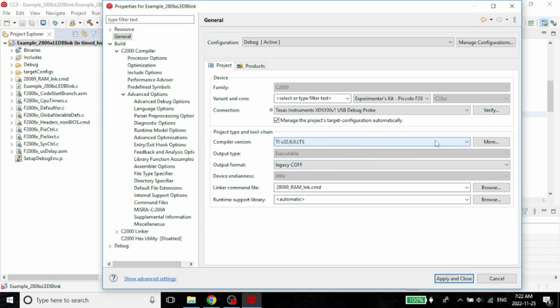Then make sure that the compiler version you're choosing, you can choose it automatically results to the latest, because once you choose Code Composer Studio, it comes with its own C compiler, right? The rest of them, it's not advisable to touch right now. I will show you these differences later. But as I said, there is this annoying little bug which was there before, which is that the --cdebug ASM data flag is no longer supported, and for that you have to unfortunately go through all these options and find out exactly where that flag has been set and uncheck that box, right?